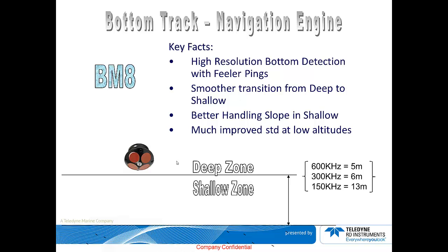Also, with bottom mode 8, the DVL becomes capable of transmitting multiple pulses with different lags, and performs what is called lag hopping, which is basically the process of finding the best lags for the quietest measurement, one at a time, separately for each beam.